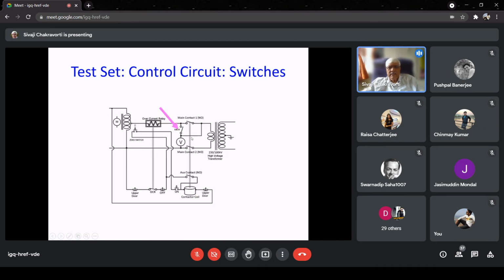Now, this is what I have not explained. Say for example, I am doing the test. I have increased the voltage and the oil breaks down and the setup trips because the overcurrent relay trips its OCR contact. Now somehow I have missed the reading. Then how do I know at what voltage the breakdown has occurred? Should I have to do it once again?